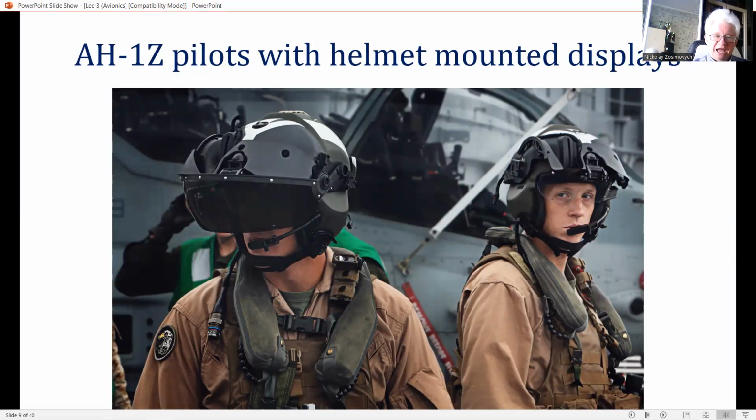First generation HMDs have been based on modifying, effectively bolting on, the HMD optical module, display source, and associated electronics to an existing aircrew helmet. This can result in a bulky build, and the total helmet weight can be high, and this is not good. Imagine you have a big G, and how can you stay alive in this situation.